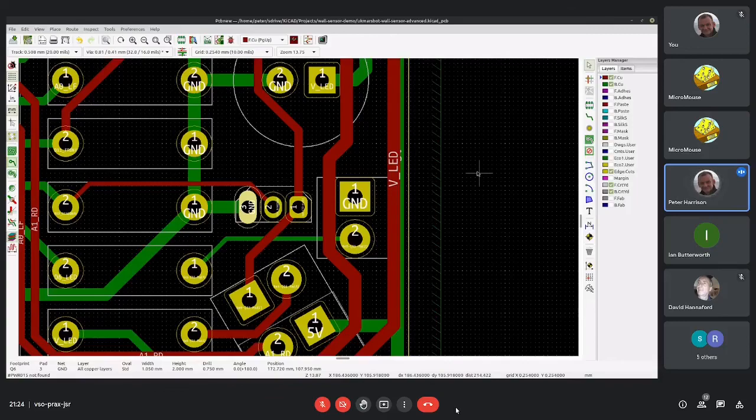So it's better to go big. Go for 8 and 8 or 10 and 10. And if you really can't fit stuff in at 8 and 8 and 10 and 10, then consider finer. The larger the spacing and sizes, the more likely it is to function and be made properly. But yes, good point.